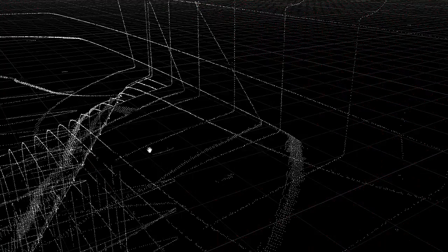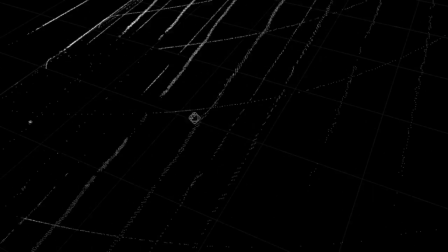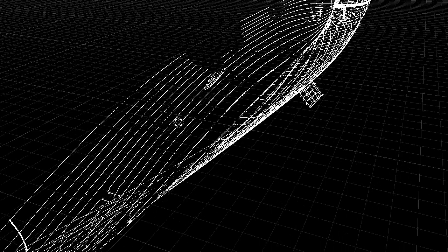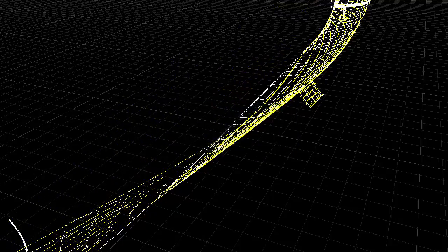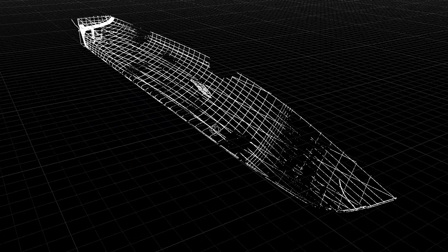For that we can use the sections. This is giving us the 3D contours of the shape that we're going to deal with, picked out in the points that are intersected with the planes that we cut through the model. This is quite a useful tool. Ultimately this data is the data that's used to generate the curves. So we can make some modifications. We can just constrain this to the port side, for example. These get reprocessed, and we can see all the designs there.